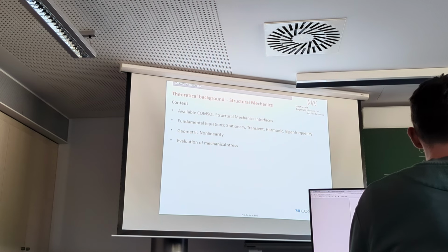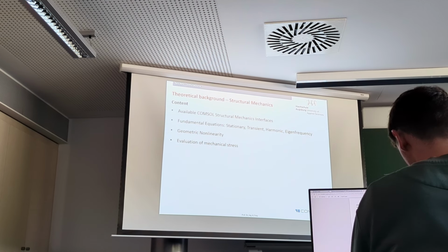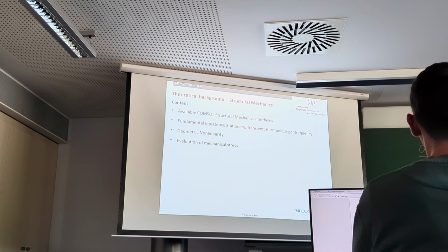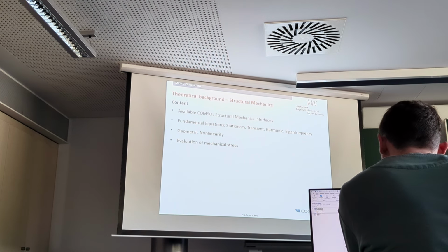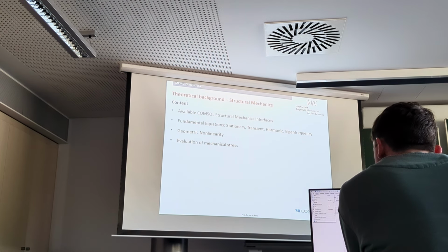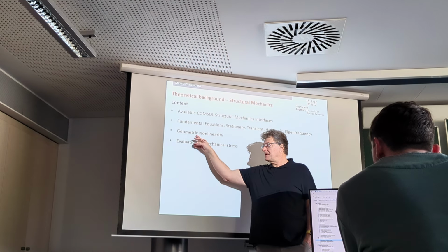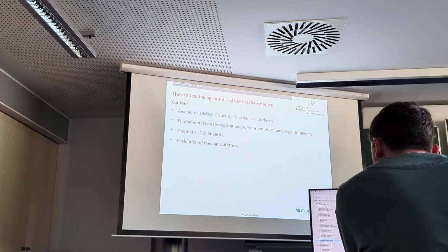And it turned out, if we do these rotations for both of the squares, one of the squares behaved as expected. They just moved, just got rotated, no stress, no strain, why there should be anything. But with the version of engineering strain, there was a lot of strain, so something is wrong, obviously. And this thing we just continue discussing and runs under that headline, geometric nonlinearity.